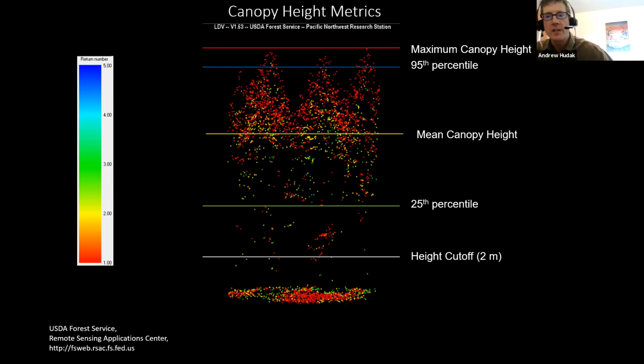But it's 3D. Things have come a long way in the last few years with software packages to manipulate this information, but still what works most effectively is to reduce this high volume information into rasters that represent the distributional statistics of the height distribution captured in this point cloud. So statistics like the maximum height, the 95th percentile, mean, etc., those themselves are efficient descriptors of the height distribution that we can use as predictors in our models.